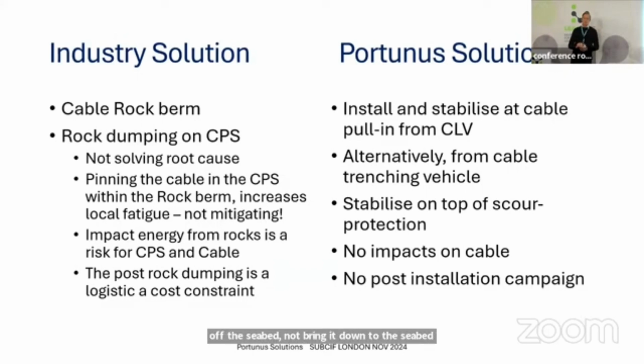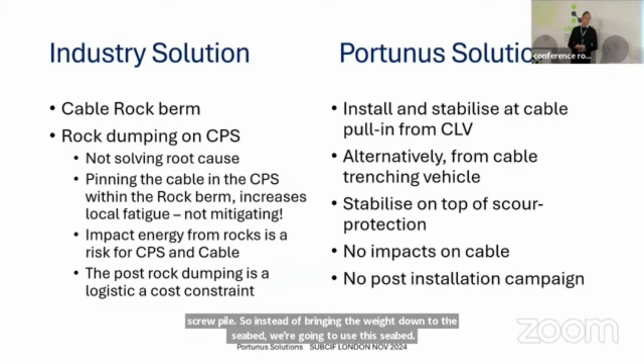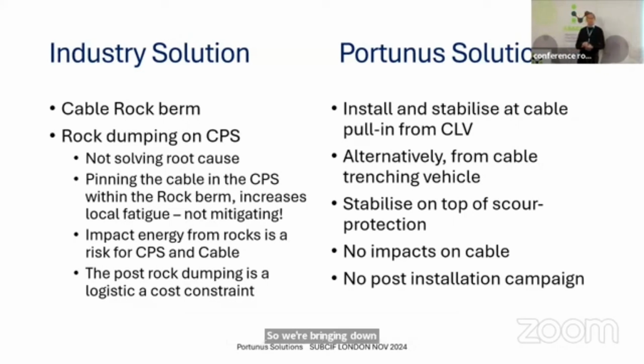So we're going to use something called a screw pile. So instead of bringing the weight down to the seabed, we're going to use the seabed. So we're bringing down a screw pile that weighs less than 200 kilos that will give us the stability of 33 tons. So that was a smart thing that we were going to do about it.